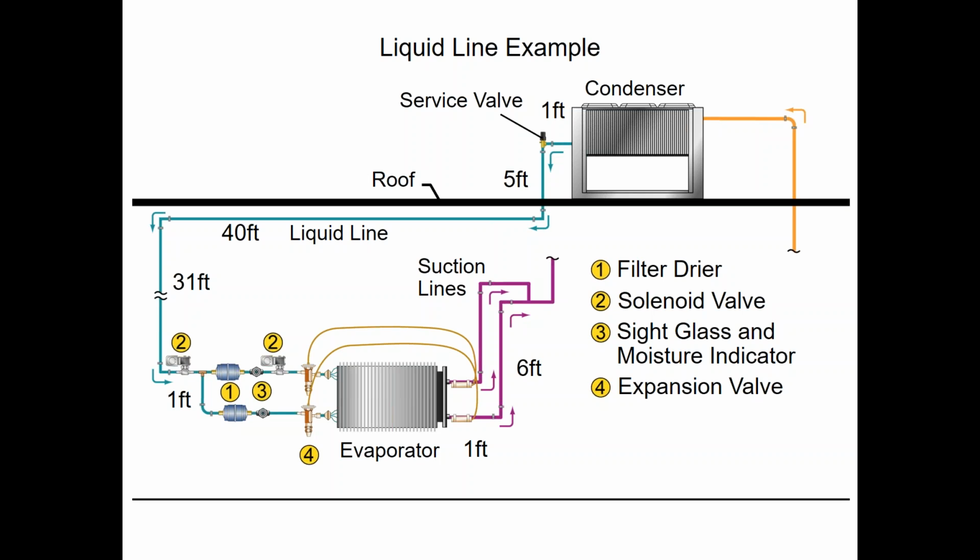The screws don't have an oil galley or sump in the compressor itself. The oil is just in circulation through the pipes and through your evaporator barrel and the condenser section. So they're both, screw and scroll, sensitive to oil level, but in different ways, because they're managed completely differently. I don't know if that answers your question or not.